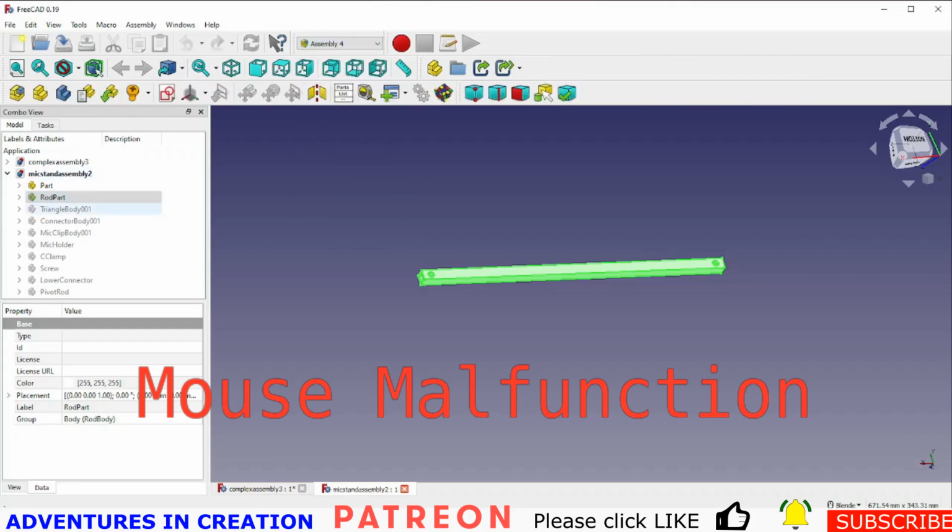Sometimes if you click on a body, it will automatically switch you from Assembly 4 back into Part Design. So just be careful with that, because if you double click on the body, it will think you want to do something to model in that, and it will take you back into Part Design instead of Assembly 4.